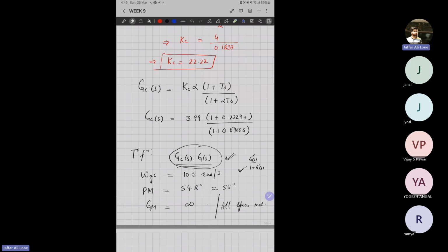So here as well, if you are not fulfilling them, either you have done it incorrectly, or you need to modify the pole zero locations based on what you have obtained. There is always a possibility of hit and trial, but at this level, I don't think that is needed. With this, I think you should be able to solve all your assignment questions.